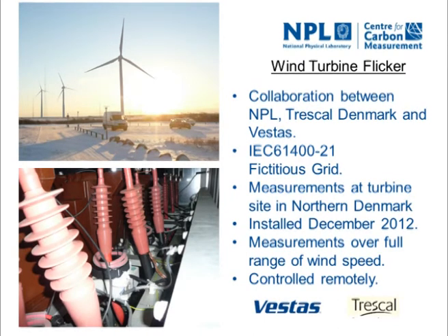And what we are looking to do is take measurements of voltage fluctuations at a full range of wind speeds from 3 meters per second up to something like 25 meters per second. And we're kind of relying on nature to provide that wind speed variation. So we have a whole set of remote measurements that we're taking, making bins of various wind speeds, measuring this very strange phenomenon known as flicker to this IEC standard,